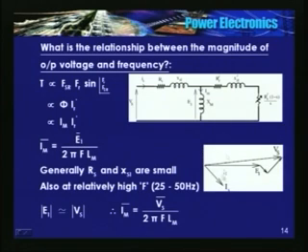Therefore Im is equal to the magnitude of the supply voltage Vs divided by 2 pi f into Lm.